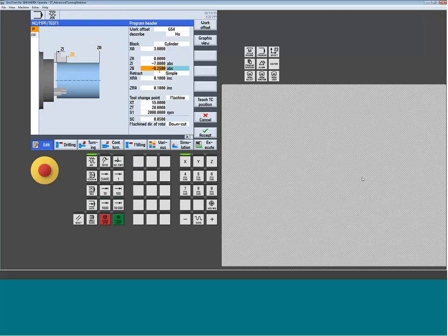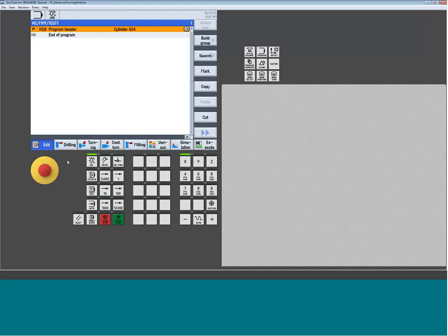But we're just going to concentrate on machining this portion of the shape. Then my retract, all the same, so I'm just going to use a simple incremental retract of 100th on both axes. A typical tool change position, so we'll just leave this alone. And my safety distance, we'll leave it at 50 thou. So I fill out the page, we hit accept.